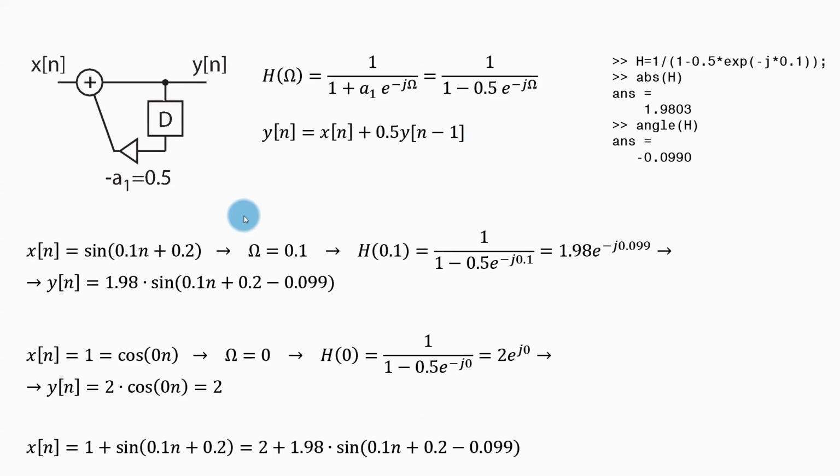You can actually use this for different sines and cosines. Let me show you one more trick. What if the input of the filter is just this constant? Well, this constant is just a cosine at zero frequency. So if I want to find out how a constant is being passed, then I need to take a look at the frequency characteristic at zero frequency. When you substitute for this filter, you will get this. The frequency characteristic is just number 2, which has zero phase. So the output of the filter is this. It's this function multiplied by 2 and not phase shifted. So if I feed this filter a sequence of 1s, I will get a sequence of 2s.